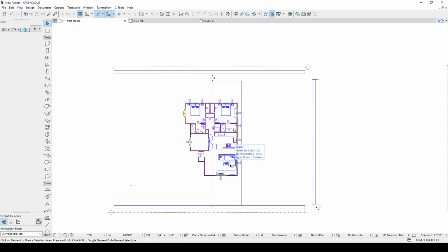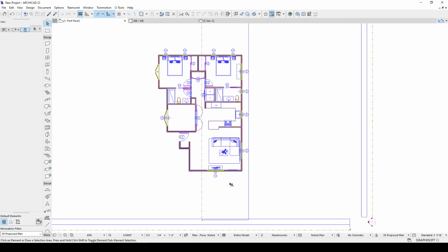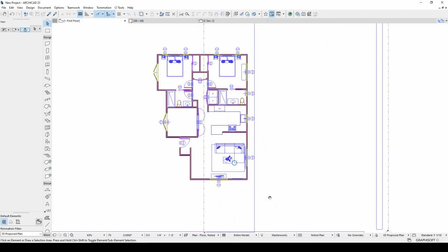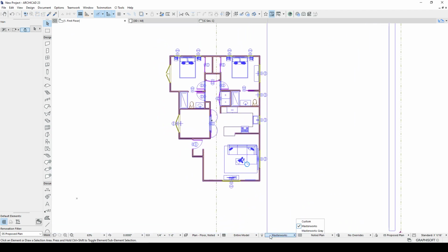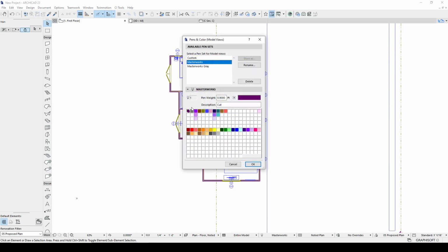The position, interior, exterior, and load bearing really aren't that hard to set up, and I could see some value in that. Here we have our pens. We talked about that in the other video. We choose to have these as our contours, these as our fills, so foreground pen, background pen.